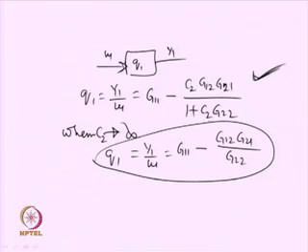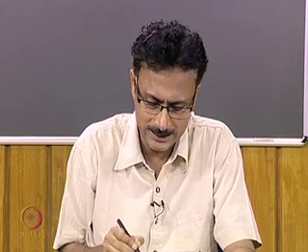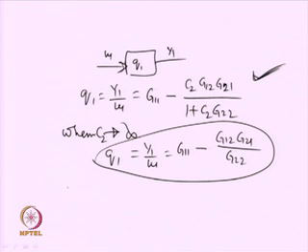I can say that when C2 tends to infinity, basically we have been able to overcome the loop interactions between the two loops, or the loop interactions have been reduced substantially, so that relay tests can conveniently be conducted, and the parameters of the two transfer function models can be identified. The equivalent dynamics: for GS, the dynamics was given by G11, G12, G21, G22.